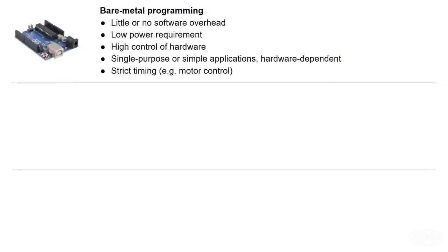The first question you might have is, why use embedded Linux at all? Let's review some options for embedded development. First is bare metal programming. This is something you might do on 8, 16, and some 32-bit microcontrollers, and many of them can be very inexpensive. Because you can tailor your code to a microcontroller, it often means you can write very efficient code with little or no overhead. You also get direct control of connected hardware.